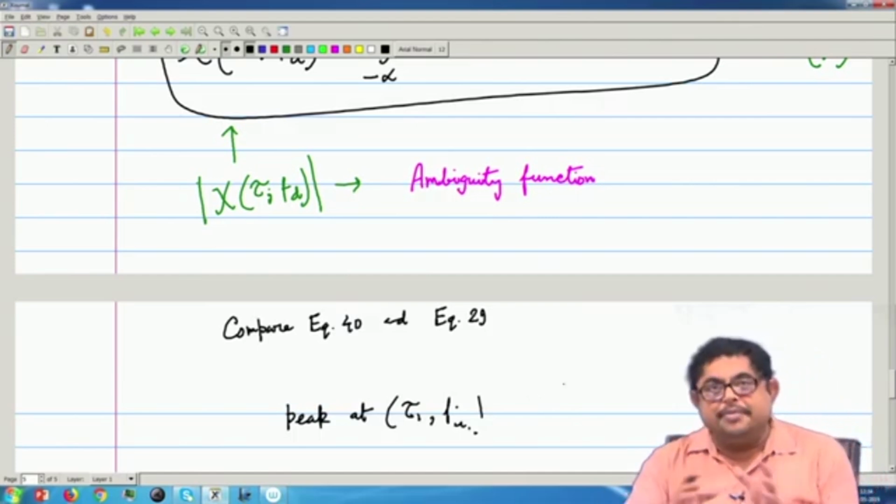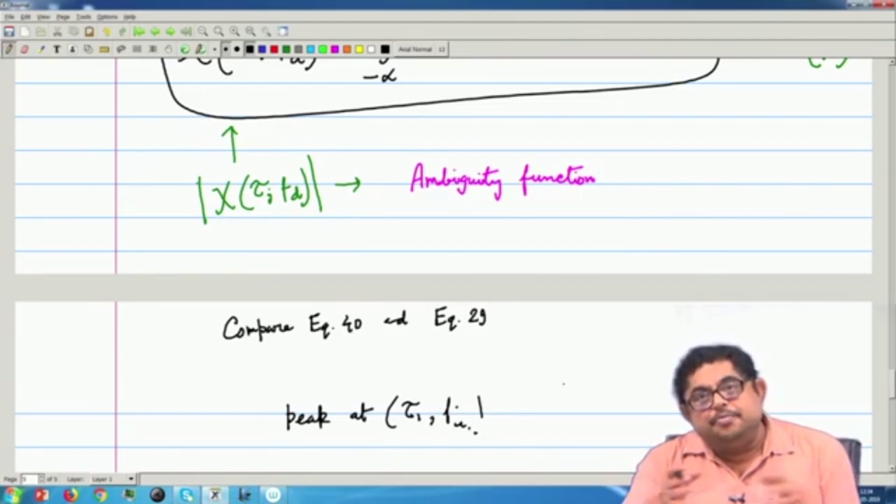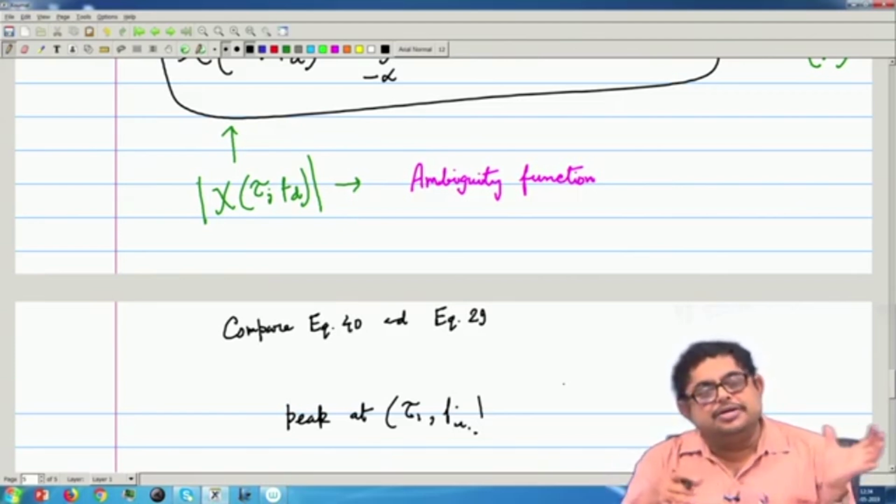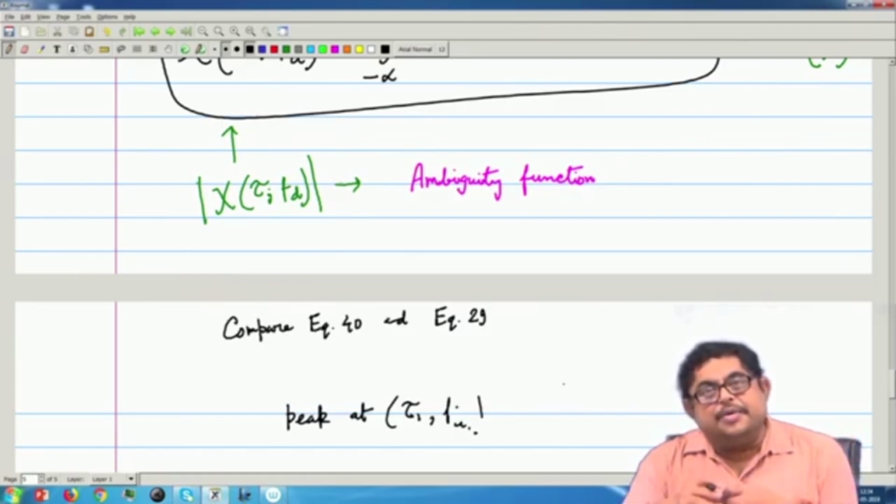Now, I am saying that we have made our journey almost through. We have seen what the best filter for beating noise is, that we found the match filter, but it is not only that, it also helps us to choose the waveform, because that helps us to have the resolution. That is why I said the waveform choice depends on what resolution you demand.